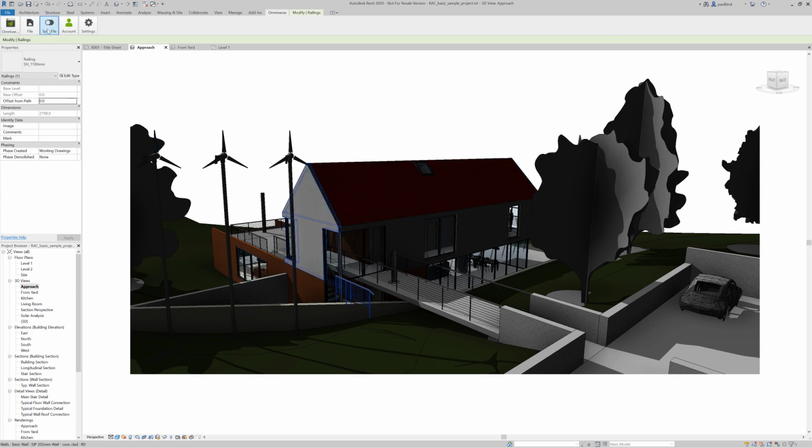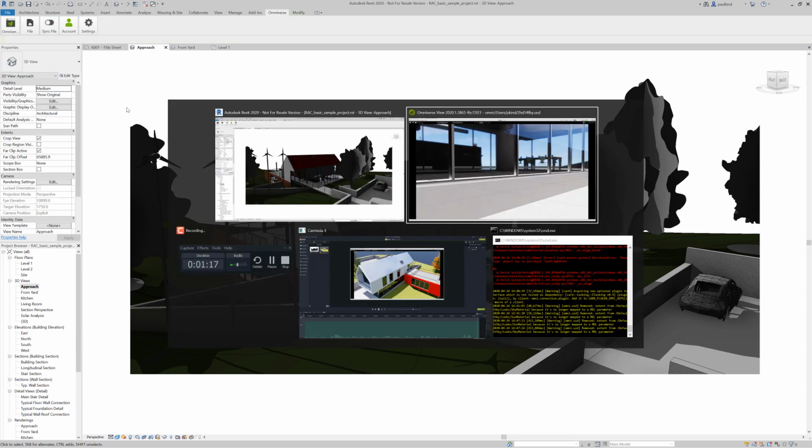Oh, and something that's rather important is when we did that Send to View, it automatically populated our location of the USD on the Omniverse server. So that was taken care of for us automatically, and we didn't even have to do anything for it. So as soon as you send, it's actually ready to be synced. So let's just make sure that Live Sync is on. Switch back over to Omniverse View.